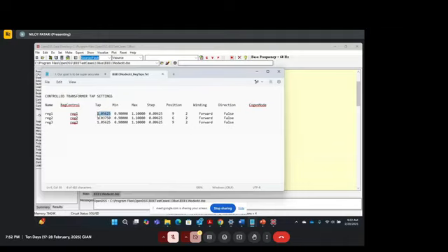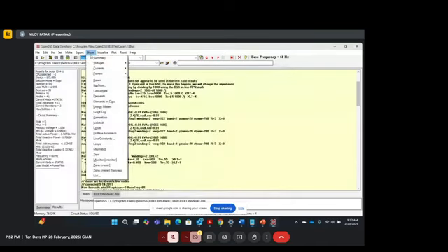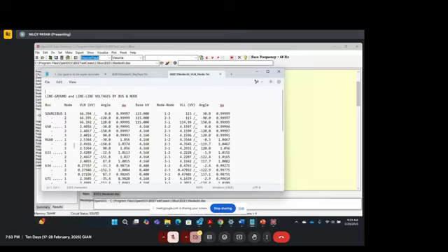How much is the voltage at reg 1? Yeah, so regulator 1, which is regulator 60, RG60, you have 1.056. So how much does it get boosted from 1? So at 650 secondary, you had just 1 per unit. And then you have this huge boost at RG60 phase 1, you have 1.056.